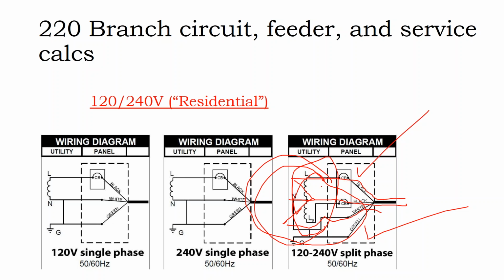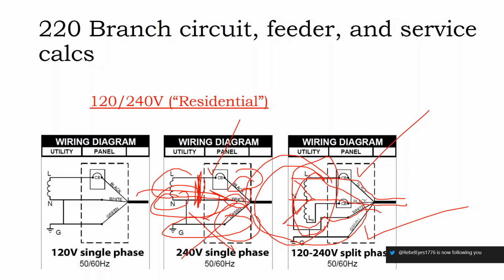And what that means is that neutral wire is being used to recirculate your system voltage, and the amount of current in that wire is as great as if one branch circuit has no continuous load on it and the other branch circuit has a continuous load and a non-continuous load. Well, what does the size of your neutral need to be? It needs to be the same size as your other circuits. It needs to be sized to carry all of the current from one circuit all the way back home.